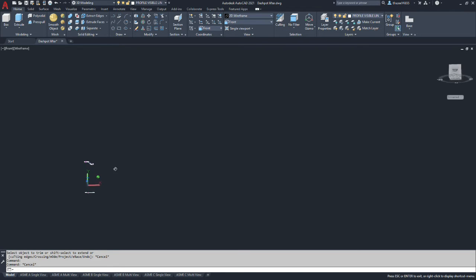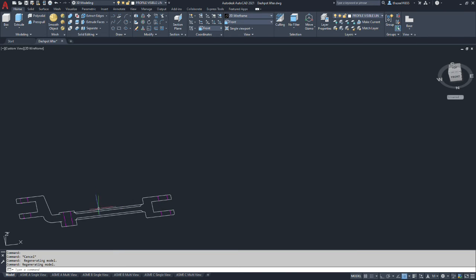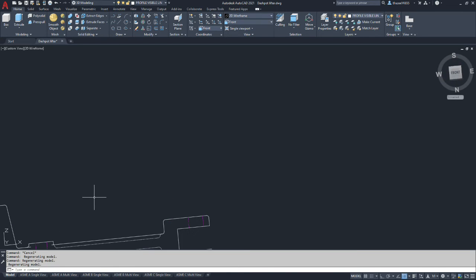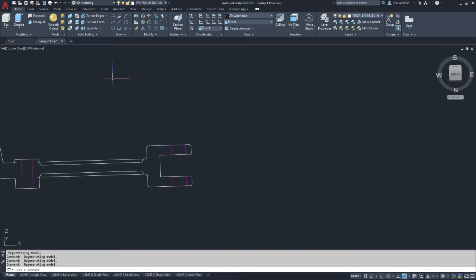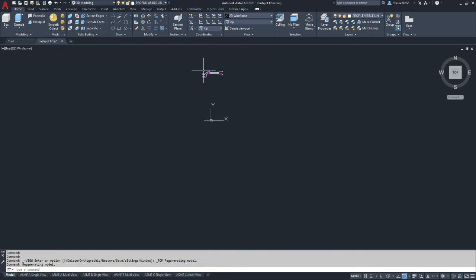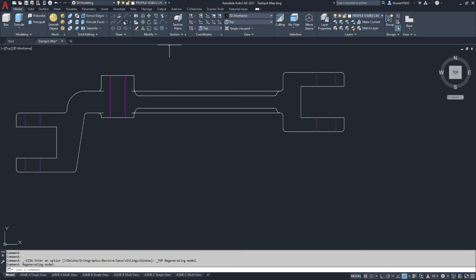Now in the example, they also broke the center of this. So we're going to do it. So we're going to just repeat that same procedure on the breakout section, which is pretty easy here. We're going to go to world coordinate system first, and then we're going to be looking at the top view. And then we're going to draw us a squiggly line using the spline tool. And I turn the object snaps and all the snaps off when I'm doing this part. So I'll just click a bunch of points.